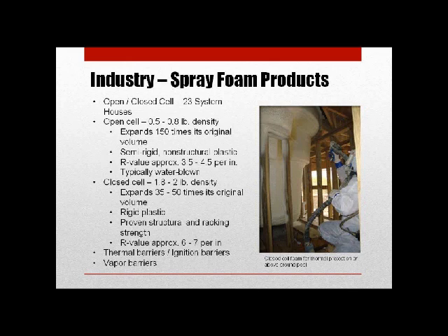The other option you have is a closed cell product, which has a higher density than the open cell, different chemical makeup, and this expands much less than the open cell. It's a rigid plastic, and it provides additional structural and racking strength to the building.